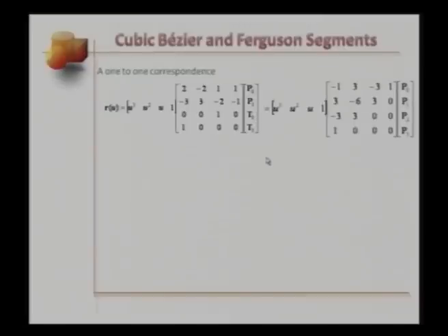Correspondingly, for a cubic Bézier curve, this 1 by 4 matrix is the same as this one in u. This 4 by 4 matrix here is the Bézier matrix, and this 4 by 3 matrix is the geometric matrix that takes the information from the 4 design points or control points that you specify. Recall that these are Cartesian coordinates in Euclidean space. So each P will have the coordinates x, y, and z, and accordingly those coordinates are going to be placed column-wise.